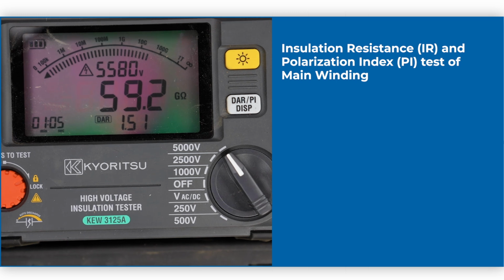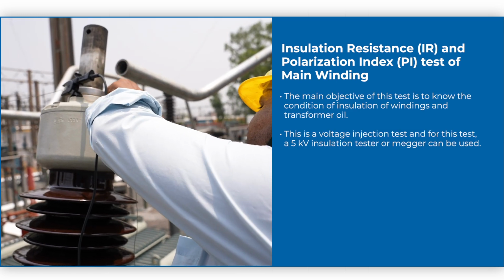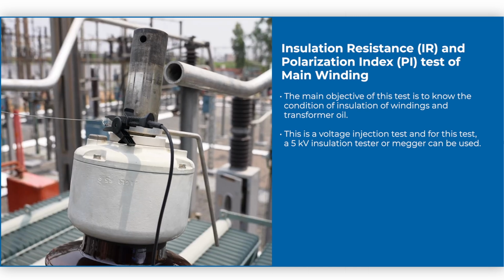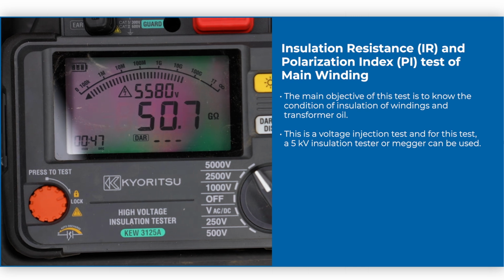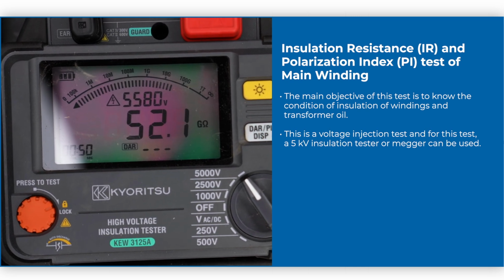Insulation resistance and polarization index test of main winding. The main objective of this test is to know the condition of insulation of windings and transformer oil. This is a voltage injection test, and for this test, a 5 kV insulation tester or megger can be used.